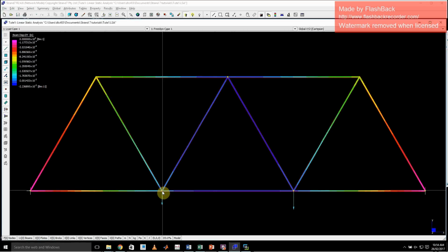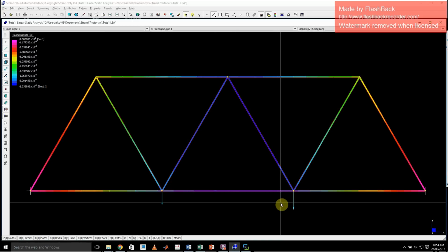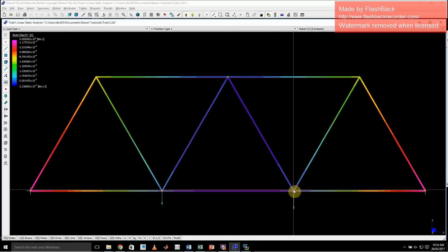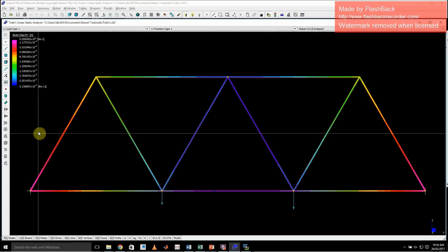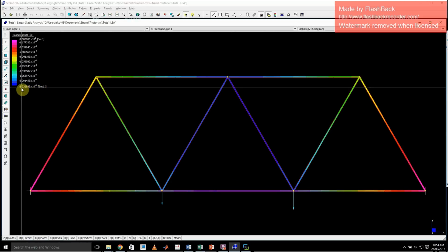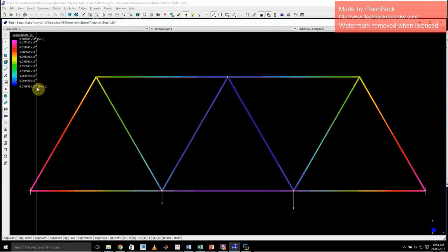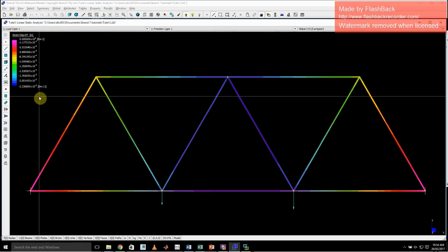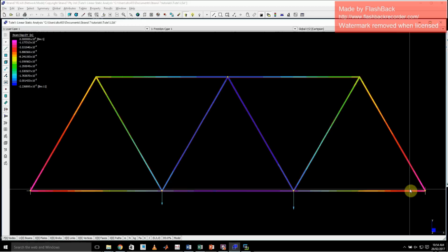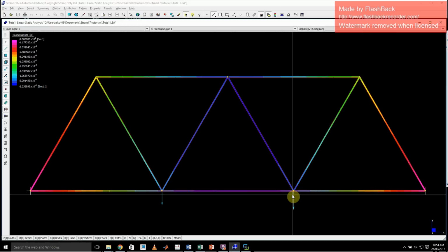So how far in the y direction everything has moved. Because if we load this bridge up, obviously it's going to predominantly just sag in the middle, right? It moved at most 2 millimeters. That was our deflection. 2 by 10 to the minus 3, we're in meters, so it moved 2 mil, and this thing is 12 mil long. There's no way that you could even see that, like not at all.